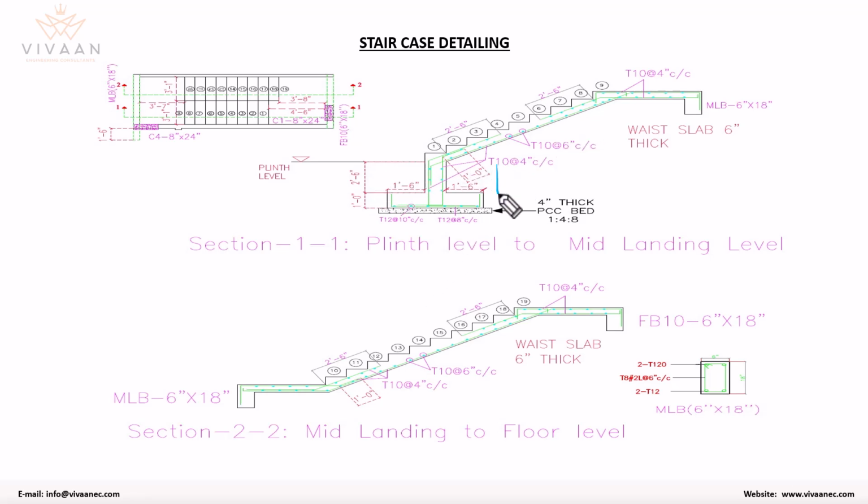So we need to properly follow the norms and properly take the depth when we build the staircase from the ground floor. People don't take the steel bars into depth, and sometimes they directly take them at the floor level. That is not a proper recommendation, because even for the staircase we need to have proper strength at the base.